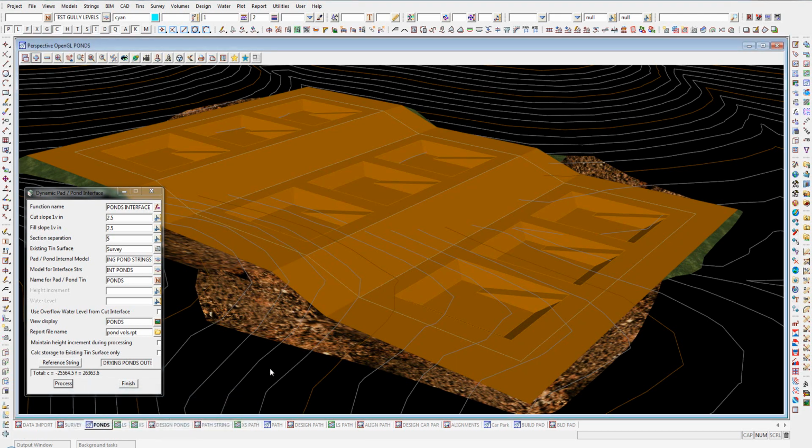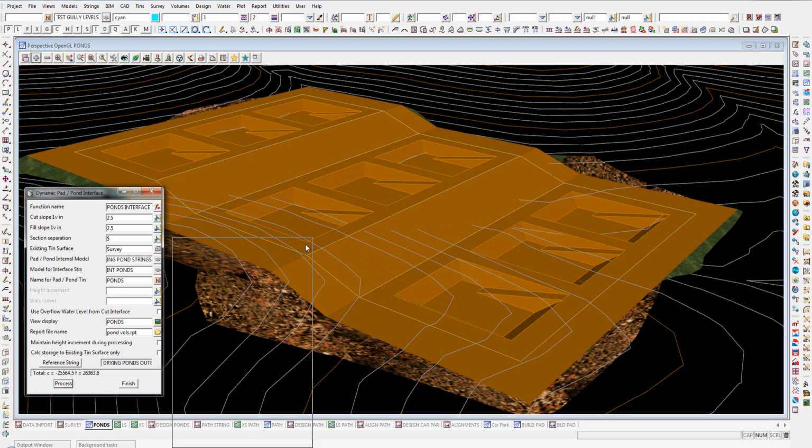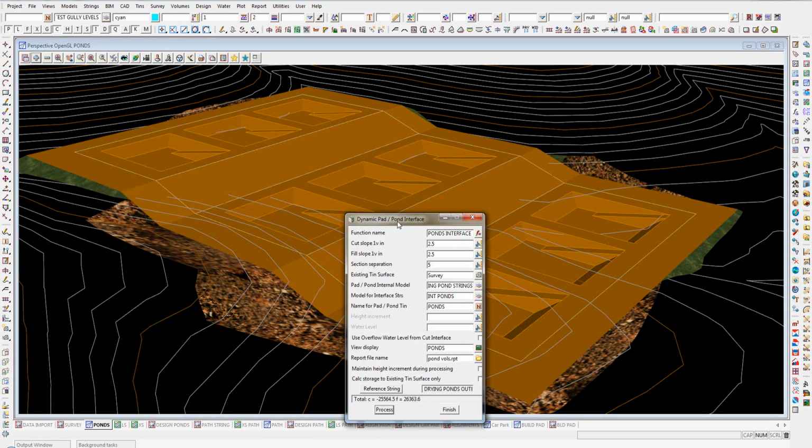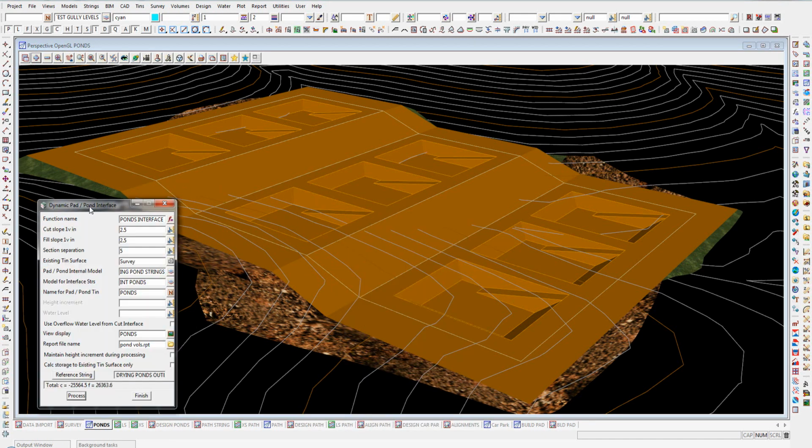That's gone through and run my initial data set through and given me an interface with cut and fill. We're in a little gully in here, cutting up there, cutting through here, and of course underneath this panel here, filling. So the idea is that I've then got a volume that I can have a look at and say I'm happy with that volume or not.